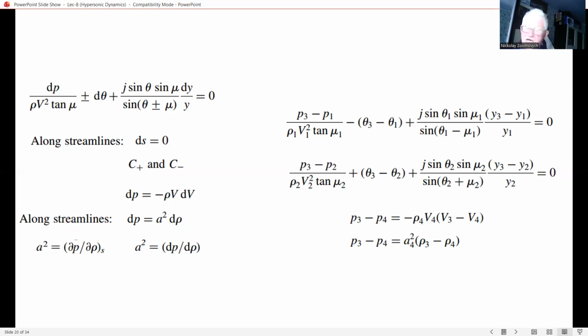The compatibility equations are obtained directly from the exact Euler equations, without any mathematical approximation or further physical simplification. Moreover, any errors introduced in the solution are numerical errors involved with the finite difference representation of the compatibility equations. In this way, the method of characteristics becomes truly exact in the limit of an infinitely fine characteristics mesh.